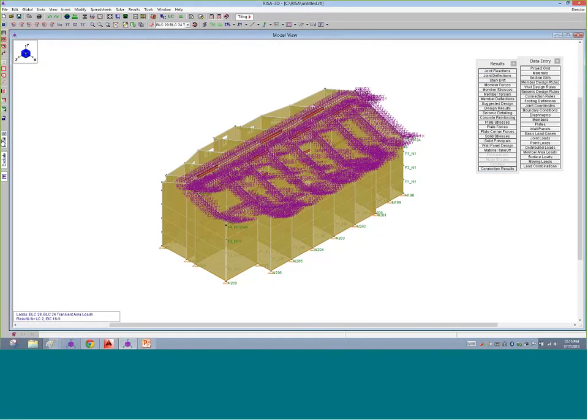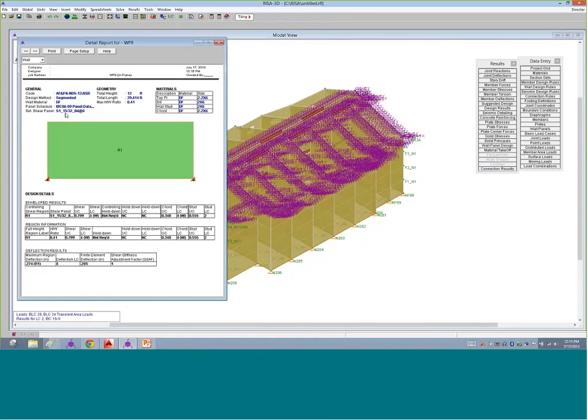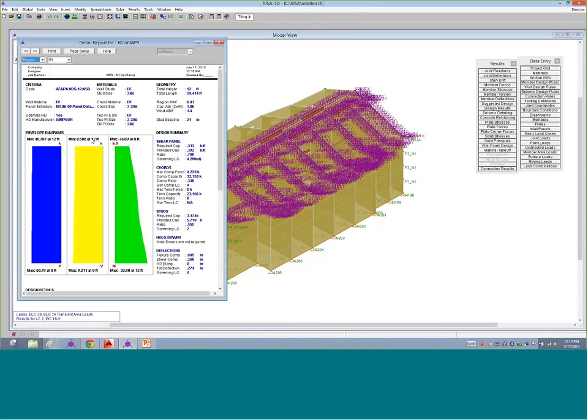So we can go ahead and take a look at the detail report and have this same wall that we were using as a representation. First of all, it got designed differently. For sure, that's a number one thing. That's a 15/32 inch thickness. And let's take a look at the region here. We see slightly different things happening. The shears, we saw 9 and change. We see 8 and change here.